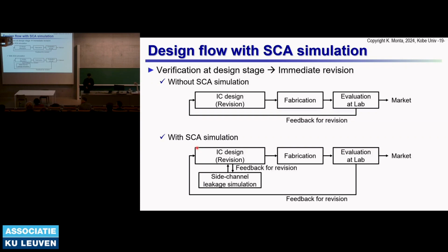If we don't have side channel analysis simulation, as I said, I have to do the IC design first, and after that, fabrication is needed, and then we have to do the evaluation at the lab. If we find a vulnerability at the evaluation stage, we have to go back to the IC design stage, and respin is needed.